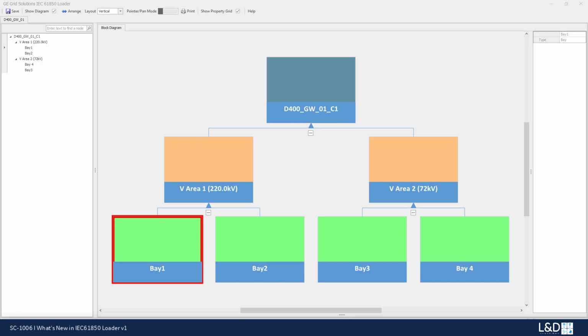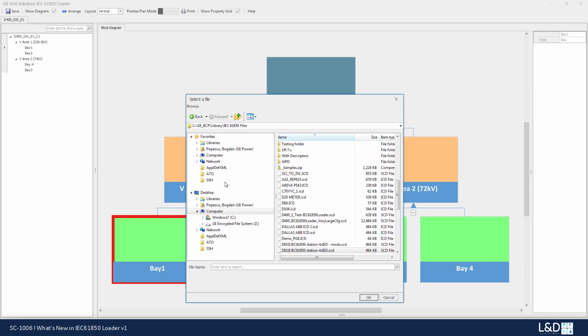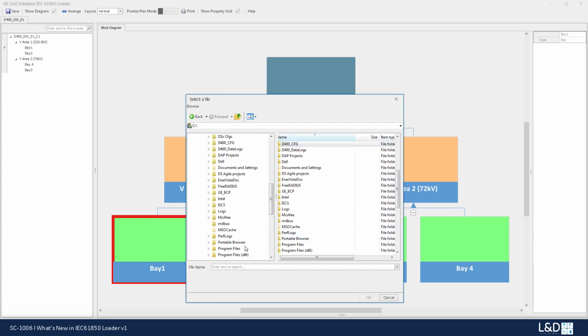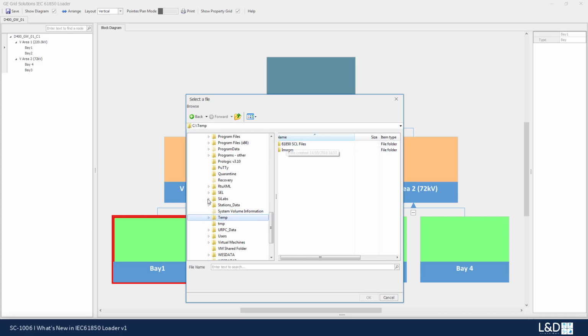The workflow specified by the IEC 61850 for adding servers to a client project configuration in an ICT or IED configuration tool is based on the SCL. This is done by either browsing for the SCL file or by dragging and dropping from a Windows file explorer.